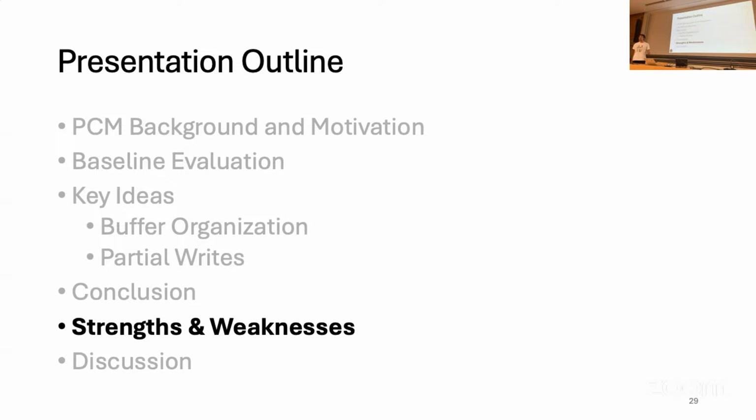Well, in the paper particularly, the authors mentioned that beyond 2 bits, it probably becomes too hard. And I think it's also controlling the exact resistance. And the big problem here is also that you have this process variation, right? So when we apply the same current to each cell, the resulting resistance might be different for different cells. And it can happen that they will move into the wrong resistance state, right?